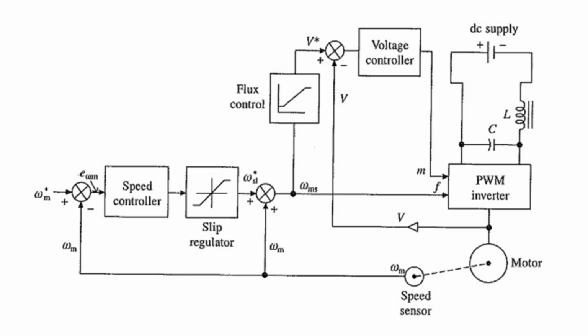So it continues from motoring to regenerative braking operation. It balances the motor torque as well as the load torque. So that is the operation of closed loop speed control of VSI fed or cycloconverter fed induction motor drives.